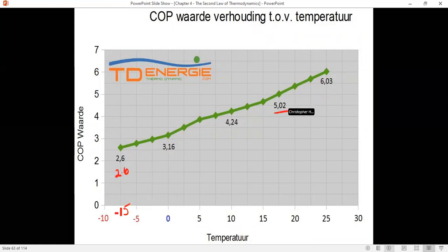As it gets warmer outside, coefficient of performance goes up. And again, thinking about the temperature of the ground, it is usually at a constant 50 degrees or about 15 degrees Celsius. So a coefficient of performance for most heat pumps would be about 4.5.